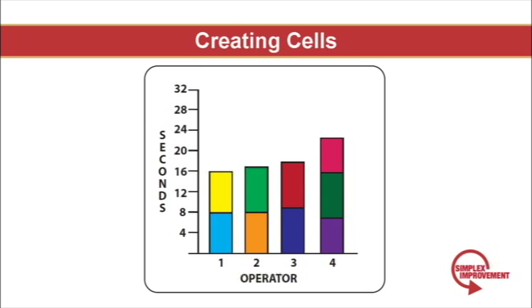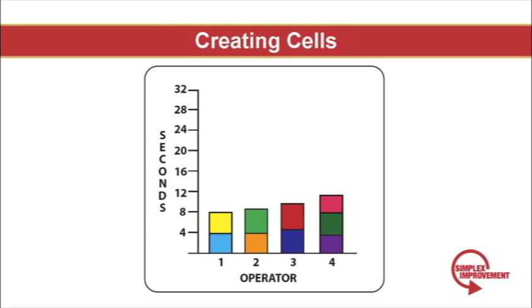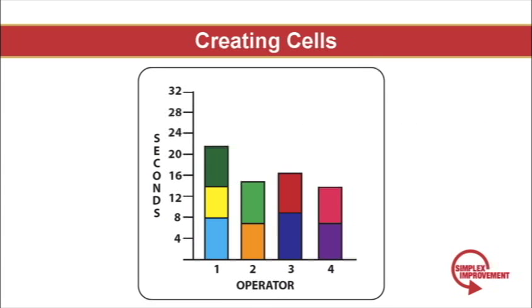So let's say the equation tells you need 4 people to meet takt. Over time, you'll naturally observe workers getting better and better at their tasks. You have a few options. The first is simply allow more idle time in your system. Idle time is obviously waste. You know that in order to drive up efficiency without overproducing, you're going to have to remove a worker. I've found that the best way to do this is to target the last worker in the sequence.